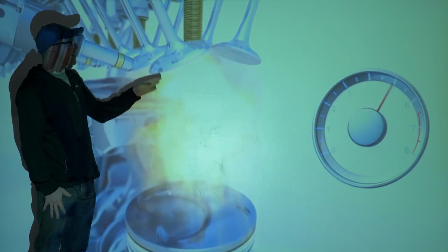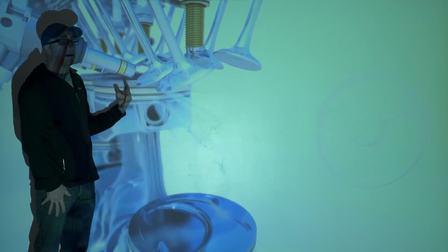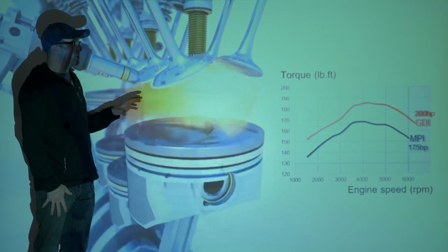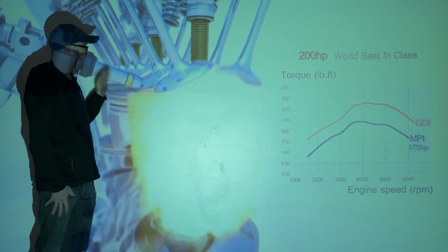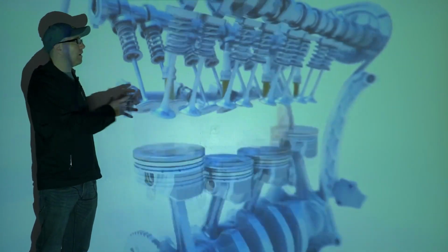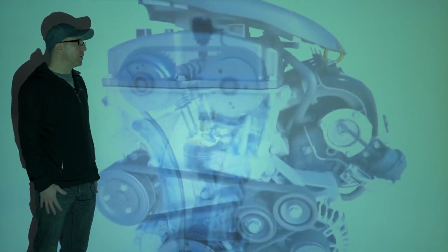They can change valve overlap, when the intake valves open and close, based on your cam phasers that can infinitely adjust. And all of this computer control requires something like direct injection. Without having the specific control of your fuel in the cylinder, they couldn't do all these things to give you the fuel economy and the power, trying to create the best of both worlds.